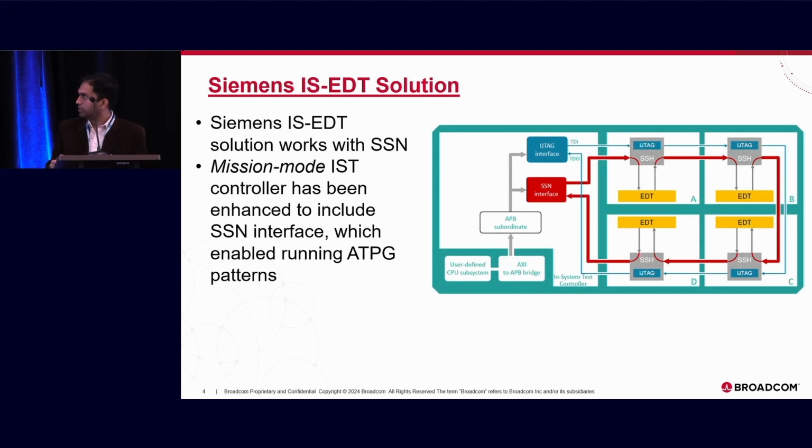Okay, so this is the Siemens IS-EDT solution. As I said, in-system test for BIST, IJTAG and JTAG has been in place for a while. We have been using it for years. The original one, which had the IJTAG interface, has now been enhanced to use the SSN interface as well. One very important point to note is that this new IS-EDT solution works with SSN only. You cannot have the EDT driven directly. You have to have SSN in place.